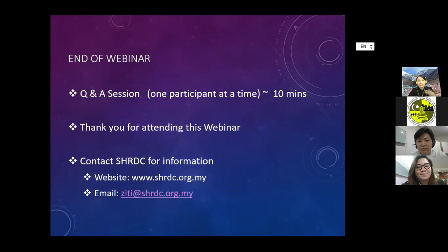But again, if you have more space, we can always make them bigger. And we make them bigger because it's easy to manufacture. If you make them too small and too fine, normally the vendor will probably charge you more because it's difficult to manufacture fine lines. So this is my answer for that.